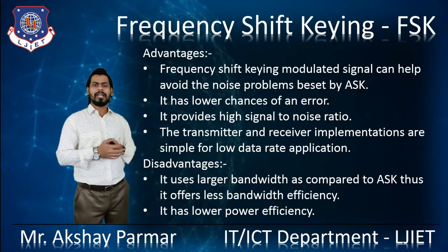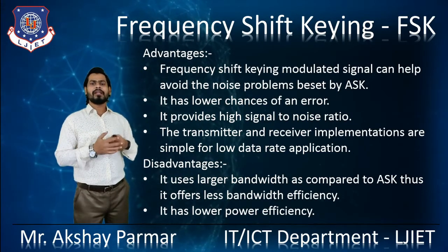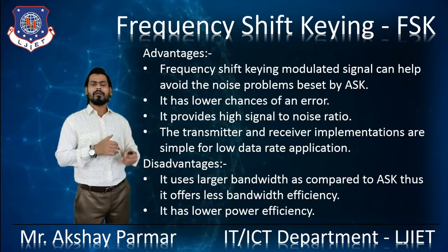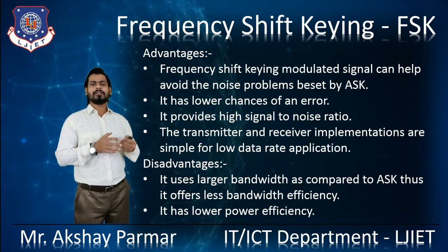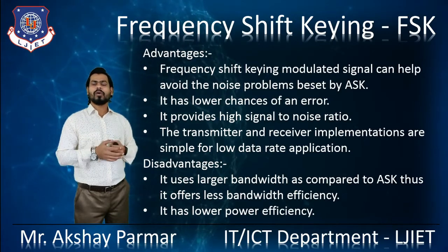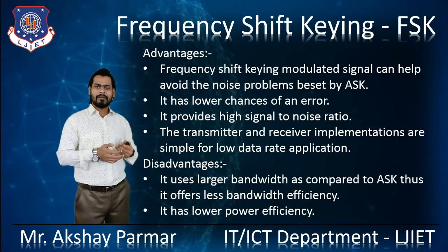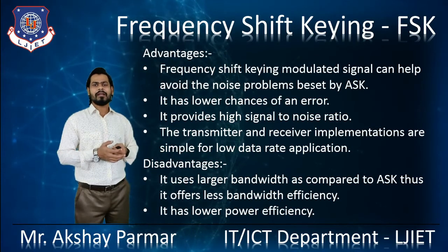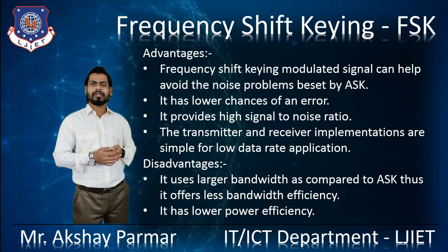After that, let's see the disadvantages of FSK. It uses larger bandwidth as compared to ASK, right? Thus it offers less bandwidth efficiency. It has lower power efficiency. These are the major disadvantages of FSK, right? This is all about frequency shift keying.